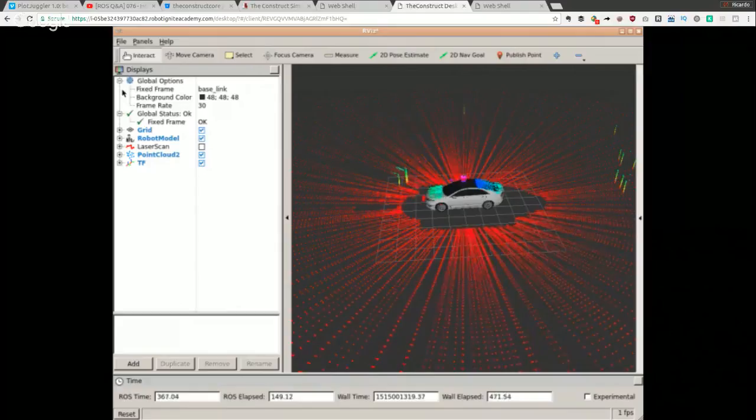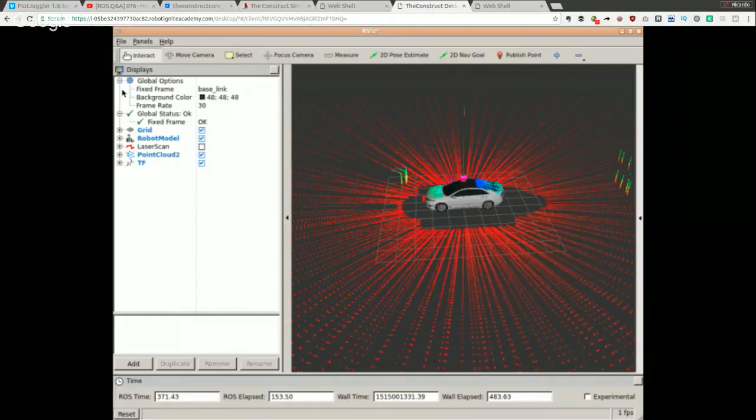Then by doing this, you will have some software that connects to the laser and receives the data from the laser. That's all. If you do that in ROS and your laser is one of the popular ones, then you are done. It's very easy. You just have to connect, usually through USB, and then launch the ROS node that communicates with the laser.